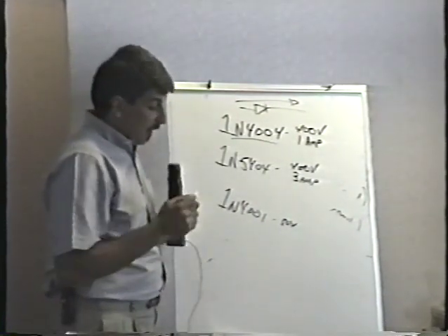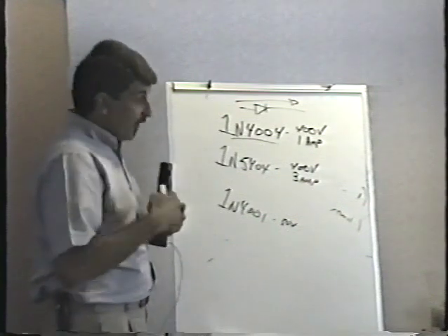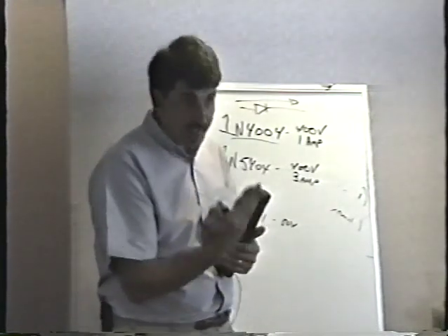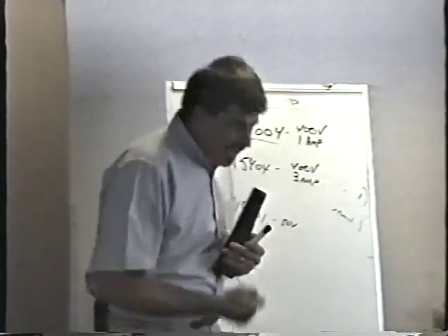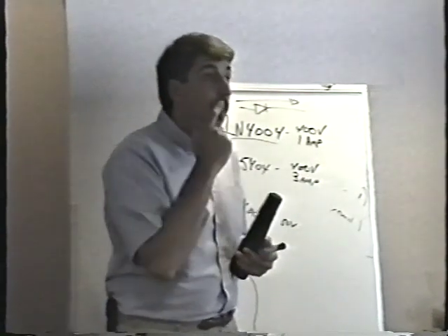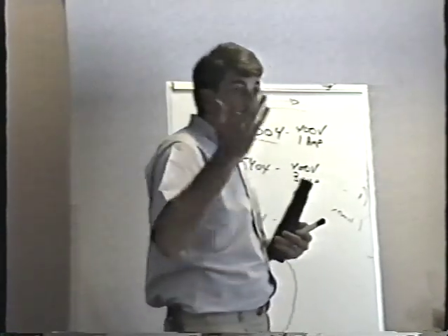No problem. What I'm saying to you is, you get to a location, you find a bad diode because it's shorted. You look at the number, it's a 1N4001. Shit, all I got is 1N4004s, and I got to go to Radio Shack. Well, you don't. You can use the 4004. You can go as high as you want.